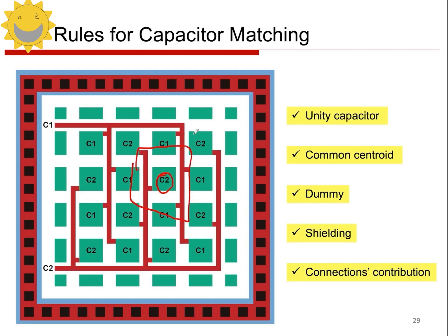Now let's look at the edge C2. After we take the dummy into consideration, the edge environment of C2 is the same as the C in the center. So in this way, it has already played the role of a unit, and the utilization rate of this area can be increased. This is something to pay attention to. Another thing to note is the details of the dummy. Some people might draw it like this, connecting everything and making the corners look like this kind of shape.